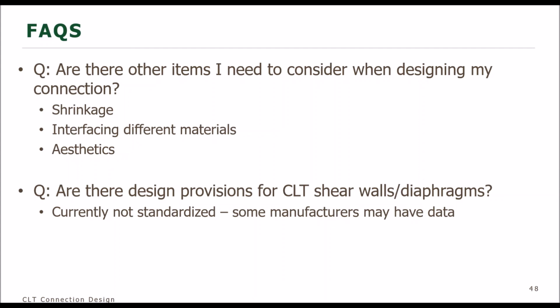So without knowing that, we would not be able to specify a load duration factor or a C sub D factor for an ASD design, or if you're in an LRFD design, that would be the time effect factor. So that's why we didn't see that appear in my examples, because these are only the unadjusted design values. These aren't for the load, the moisture, and things like that. Yep. Seismic or snow or whatever. Yeah. Okay, one last question.